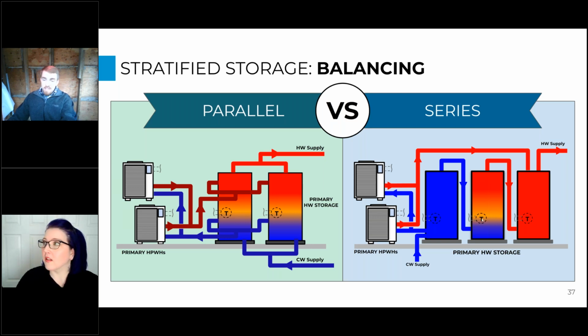So then as that tank is full, now that hot water is going to work its way back to this first tank, and the heat pump will shut off once it sees hot water entering the heat pump. So now we've backfilled all 3 of these tanks with hot water.